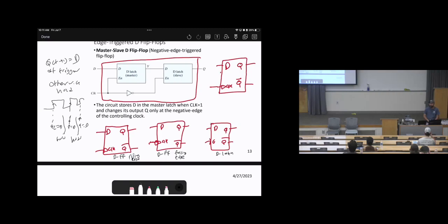Okay? Does this make sense? So when we determine it's a rising edge or falling edge, we say that at this edge there will be updates. Otherwise, hold. There is no forbidden status. There is no other tricky status. So actually dealing with flip-flops will be much easier than dealing with latch, because in latch you need to detect what's happening inside the on time. But here, don't worry about it.